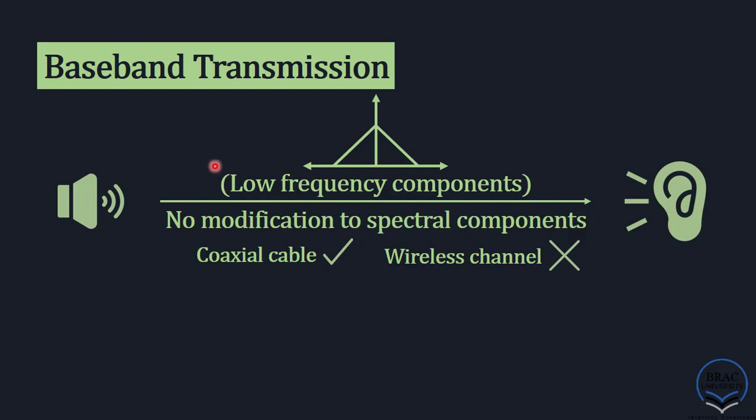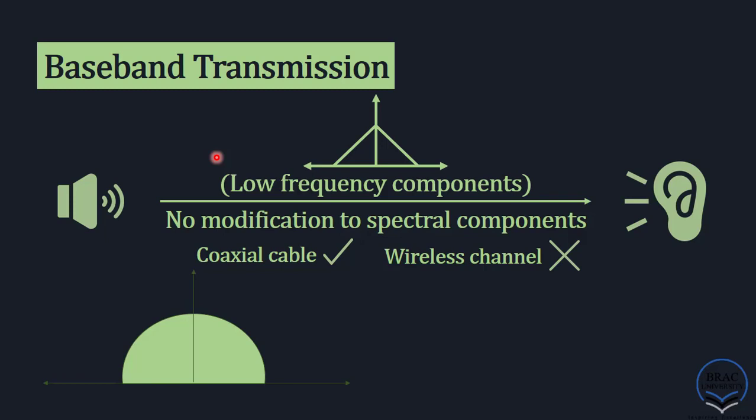So the other option is discriminating them in frequency domain. But the problem is, as you know, for human speech, bandwidth is limited from 0 to 4 kHz. So actually in frequency domain, these signals are also overlapping. Let's demonstrate it. Let's say this is our frequency axis. The message of the first signal for the first person is this. This is the spectrum of the first message. This is having the frequency spectrum from this to this. Maybe this is the 4 kHz point. The next person has a similar sort of bandwidth. Of course, the shape of the spectrum is different because the signal is different. But if you look at the bandwidth, then the bandwidth is similar.